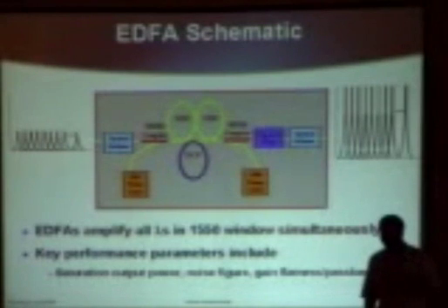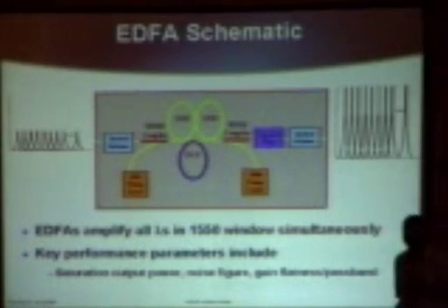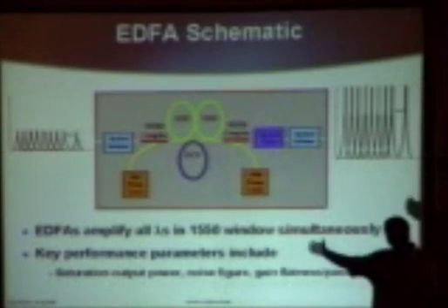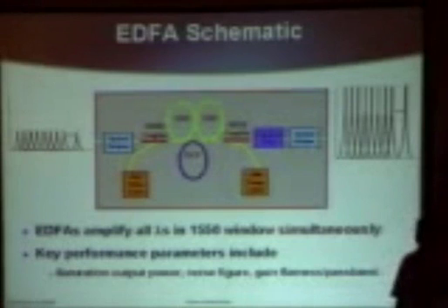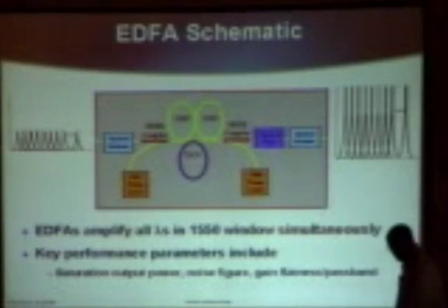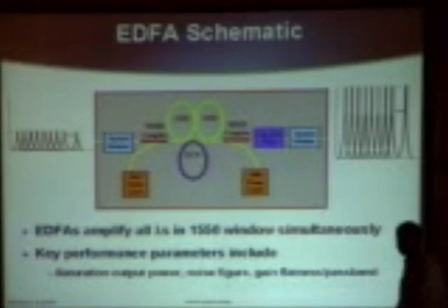So we see now, for example, new amplifiers being offered that will support 160 wavelengths. You start off with 16, 32, whatever you want. Just keep growing your system. You put the fiber in, you put the amplifiers in, and you're good to go until you hit 1 to 2 terabits today. And WDM will probably, I think, in the next couple of years, we'll see 10 terabit systems on a single mode fiber.